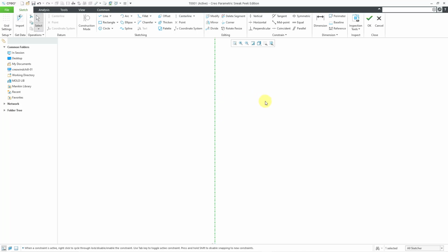What you're doing in sketch mode is creating a profile for a revolved feature. There are a few different rules, peculiarities, that you have to follow. First off, everything that you sketch has to be on one side of the vertical center line, just like in Sketcher when you're trying to create a sketch for revolving. But for your tool, everything has to be on the right side of the sketch. So that's one of the things.